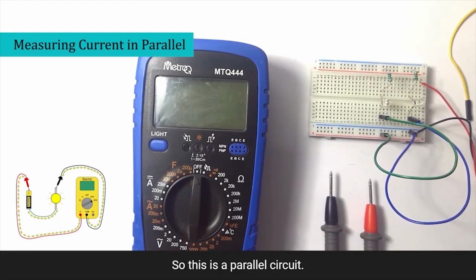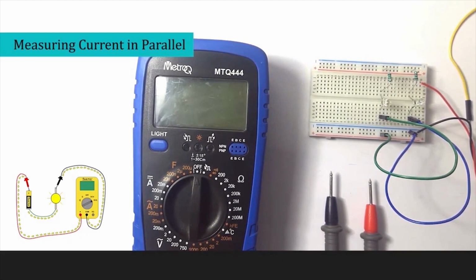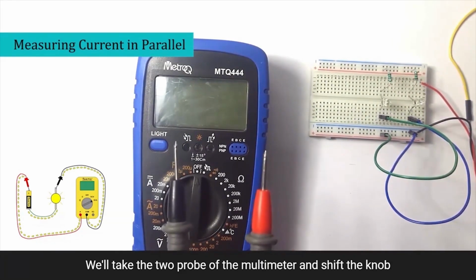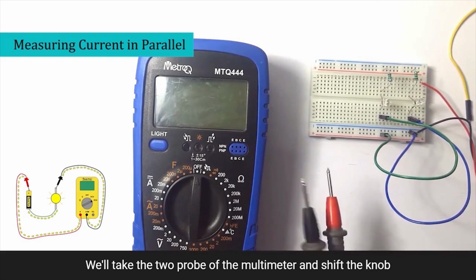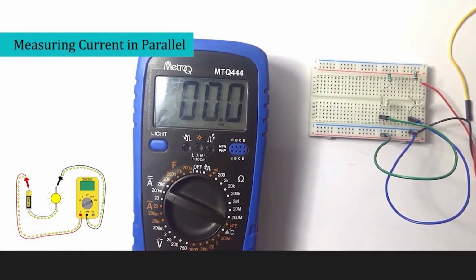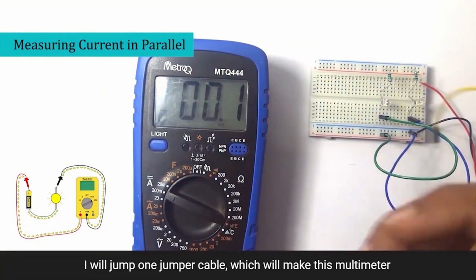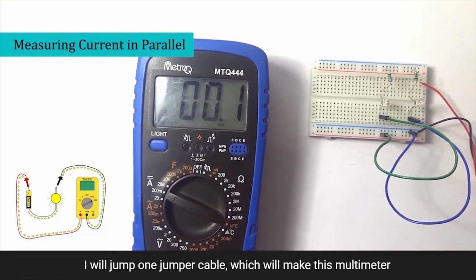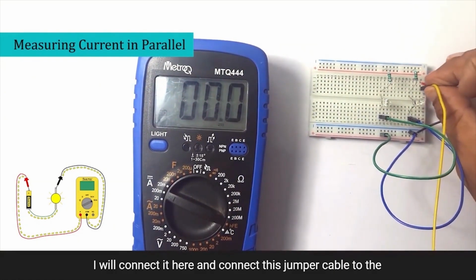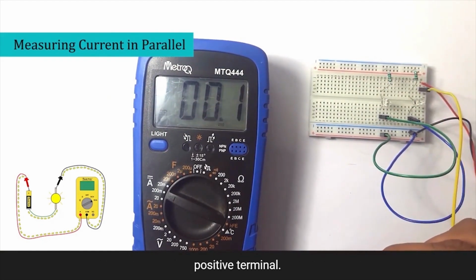So this is a parallel circuit. Now let's check current across the parallel circuit. As we know, the current divides in a parallel circuit. So let's check. We'll take the two probes of the multimeter and shift the knob to the current part. This is 200 milliampere, where it can measure up to 200 milliamps. I will jump one jumper cable which will put this multimeter in series. I'll connect it here and connect this jumper cable to the positive terminal.